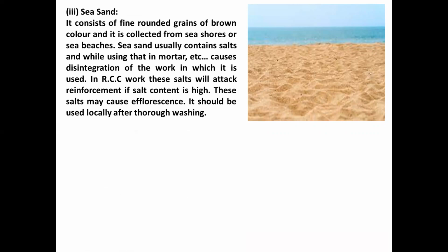Just take a look at this picture. Yan ang halimbawa ng sea sand na larawan natin o imahe natin. It consists of fine rounded grains of brown color, and it is collected from seashores or sea beaches. Sea sand usually contains salts, and while using that in mortar, etc., causes disintegration of the work in which it is used. In RCC work, the salts will attack reinforcement if salt content is high. The salts may cause efflorescence. It should be used locally after thorough washing.